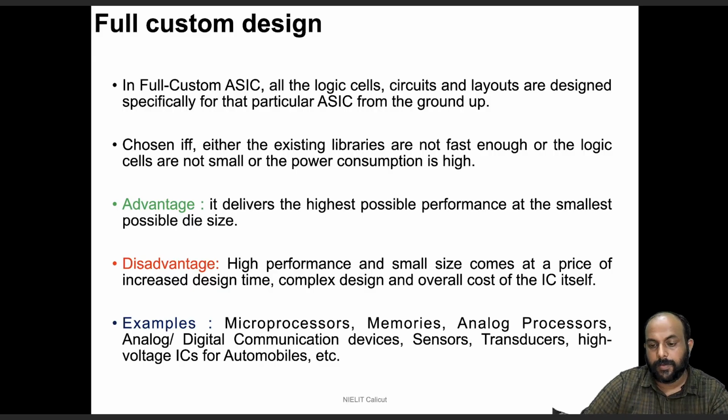This particular way of designing an ASIC, application specific integrated circuit, is called a full custom design. The advantage here is that it can target any particular performance, and it delivers the highest performance at the smallest possible die size and perhaps at the smallest possible power consumption. So it is just like customizing your product.